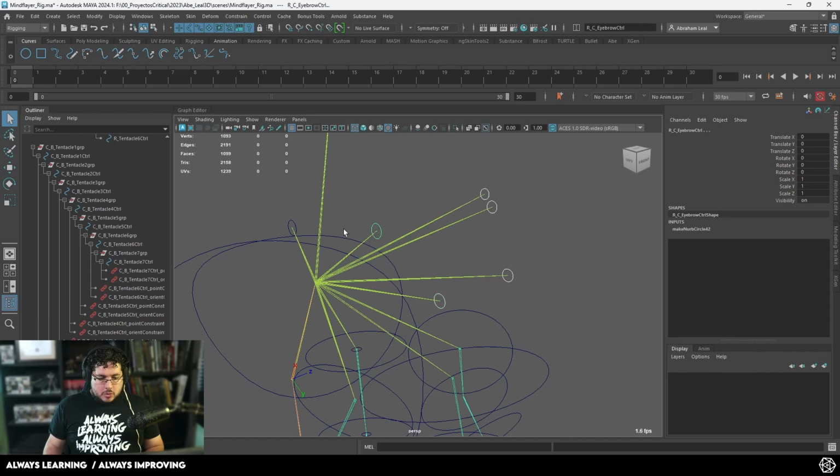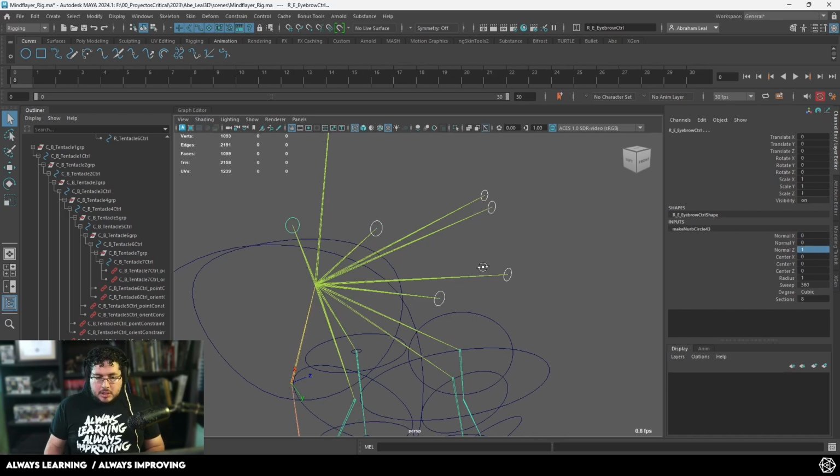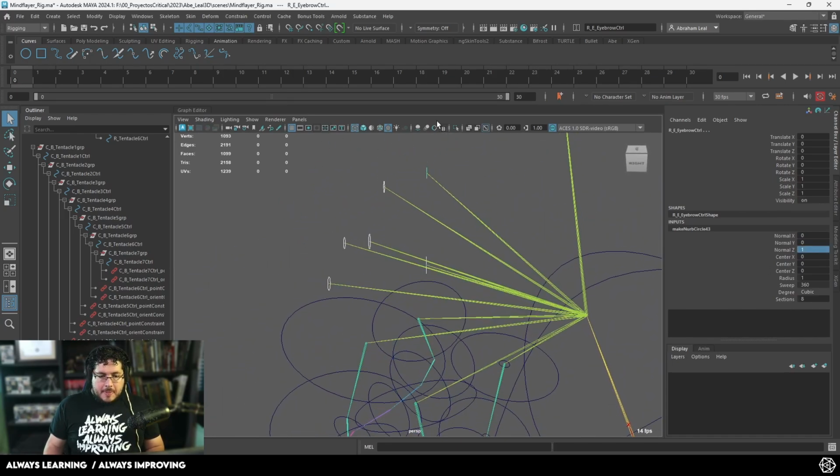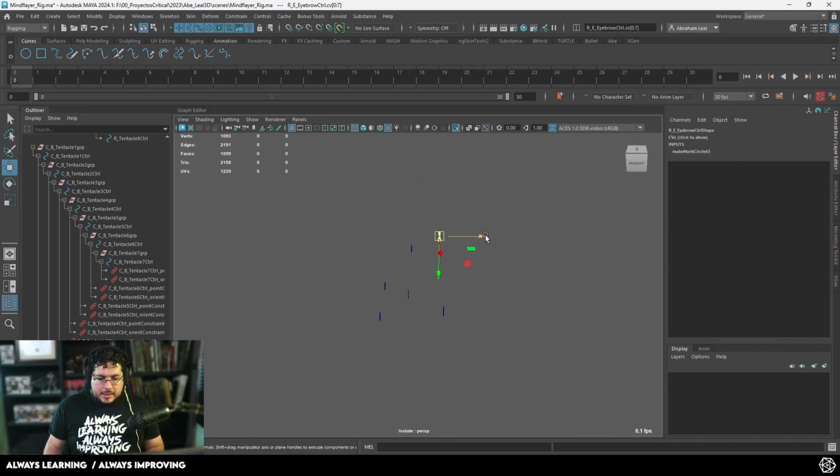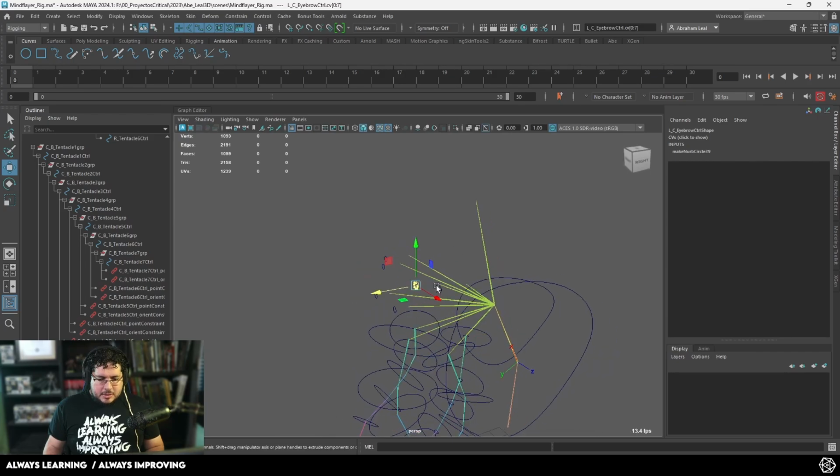So I'm going to grab all of the curves right here. The first thing I'm going to do is change their rotation, so instead of X0, it's going to be Z0, so they're facing forward, as you can see. Then I'm going to isolate all of them, go into control vertex mode, and push this. In order to make this as precise and exact as possible, I'm going to go to my grid snap and snap all of them one grid forward. So there we go, that's the position right there.